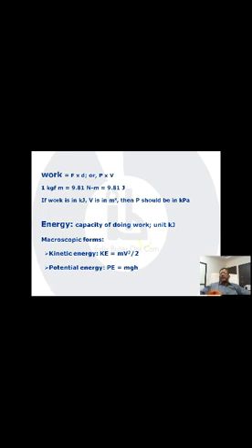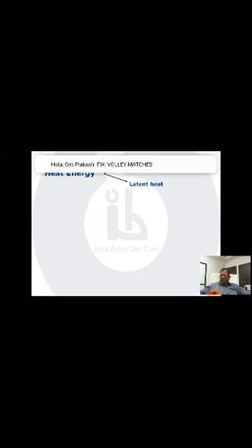Okay, talking about heat energy, this is the most important energy for us. So let us find out how to assess the heat energy. There are primarily two forms of heat energy available in a boiler system. One is the sensible heat. Sensible heat is the one where you heat it, the temperature goes up, right? You can sense it. Another is the latent heat, which you put in when there is a change of phase, from solid to liquid, from liquid to gaseous. Primarily for us it will be from water to vapor form.